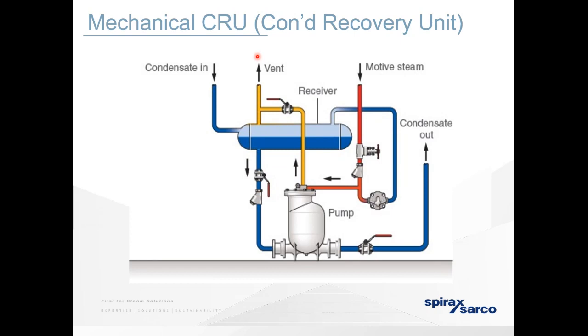If you've got a process where it needs to be clean because you have direct contact of steam with product, so we would say that steam is then an ingredient. For instance, noodles sometimes get steam injected directly to them. Cornflakes as well, Weetabix, those kind of things. You're actually using steam as part of your product, so the steam would need to be as clean as possible.